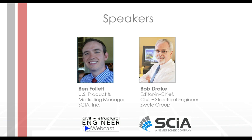Okay. Next question, how does SCIA handle nonlinear material analysis? So it depends on the type of nonlinear material analysis that we're talking about. SCIA handles nonlinear geometries when it's doing second order analysis. Those are based on standard second order analysis techniques, the Timoshenko, the Picard, the Newton-Raphson methods, both for 1D members and 2D members alike, and creating nonlinear combinations.